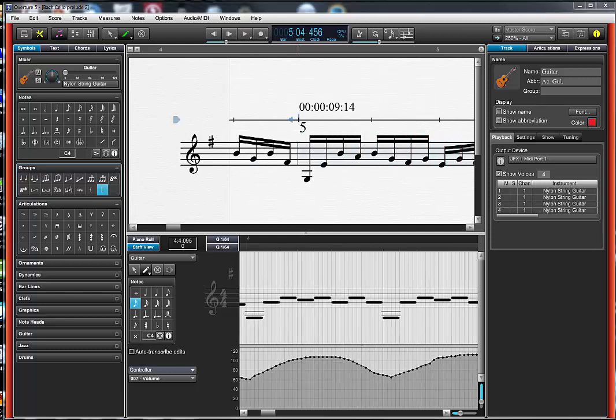So there you can hear the volume of the piece is now being controlled, as we would expect in a plugin, by CC7, only I've actually done that through converting it to voltage and using that voltage as the controller through a voltage controlled amplifier. And if I had a MIDI interface that could do more than 1 CC, and some of them are out there like that, I could do a lot more sophisticated control of the modular through Overture, through maybe a few CCs at the same time.